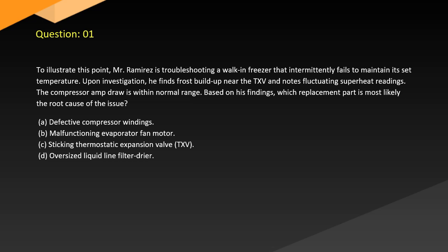Question 1. To illustrate this point, Mr. Ramirez is troubleshooting a walk-in freezer that intermittently fails to maintain its set temperature. Upon investigation, he finds frost buildup near the TXV and notes fluctuating superheat readings. The compressor amp draw is within normal range. Based on his findings, which replacement part is most likely the root cause of the issue?